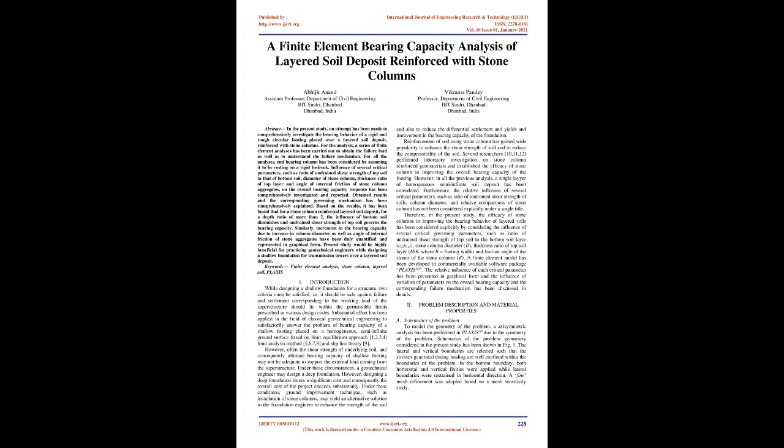Under these conditions, ground improvement technique, such as installation of stone columns, may yield an alternative solution to the foundation engineer to enhance the strength of the soil and also to reduce the differential settlement and yield an enhancement in the bearing capacity of the foundation. Reinforcement of soil using stone column has gained wide popularity to enhance the shear strength of soil and to reduce the compressibility of the soil.